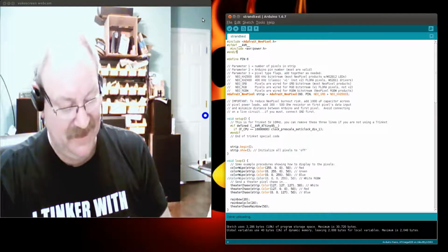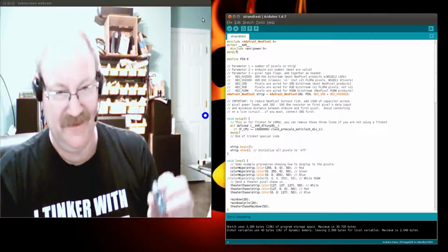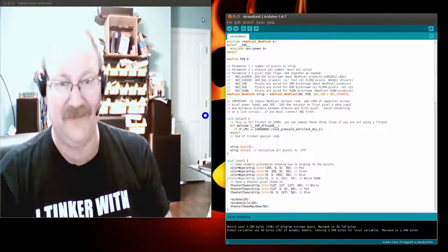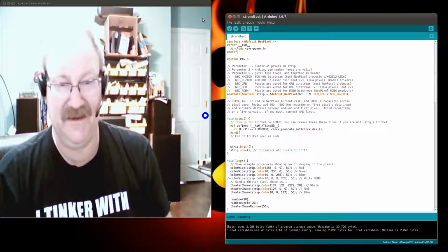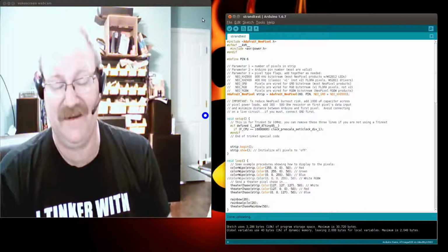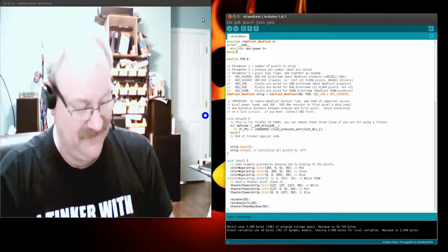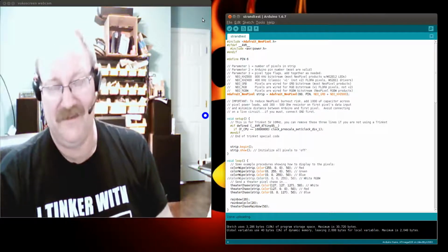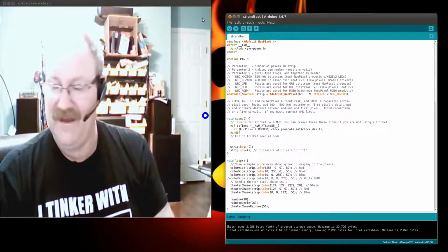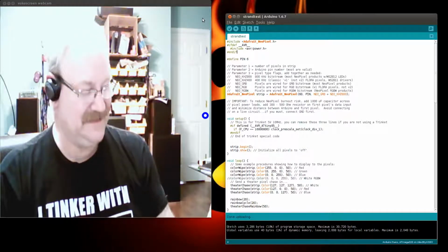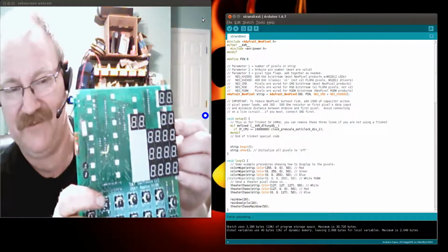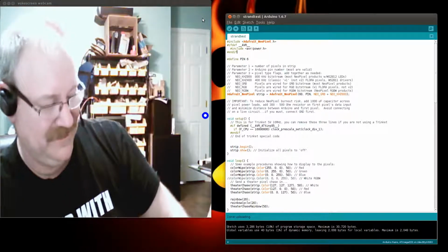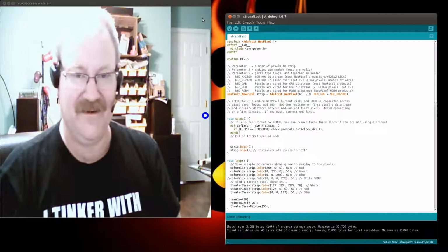But anyways, we're going to try to stick really close to what actually was. This little Nano has 8K of ROM, just like the AGC did, and 2K of RAM, pretty much just like the AGC did. Although it's 16-bit, and it has a little bit different architecture for storing negative and positive numbers, and we'll talk about that later on. But we've got a bunch of other things to go through between here and there. Next time we're going to talk about testing the actual 7 segments and the driver chip that drives those, and we'll go get the library for it and start playing around with that in our next video.